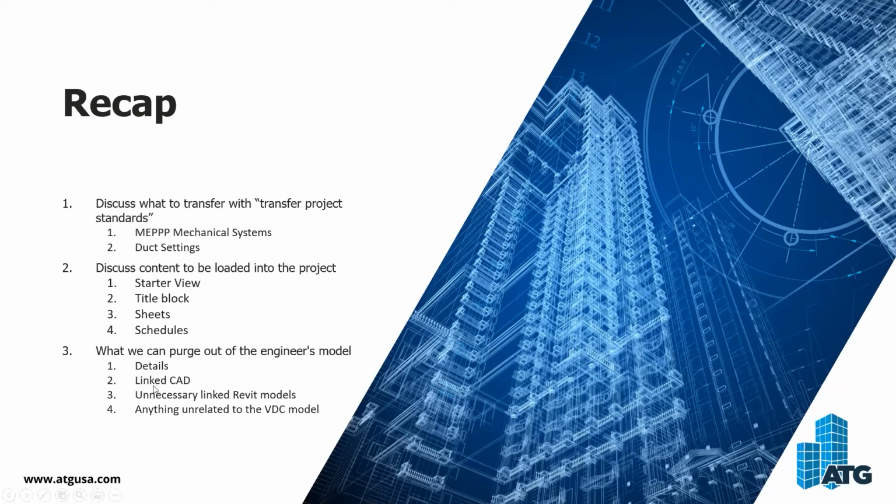But things to purge out of most of these engineering models would be your details, any linked CAD stuff, because I don't know about you guys, but I don't receive CAD very often in that initial kickoff of handing over the models. And then any other unnecessary linked Revit models.